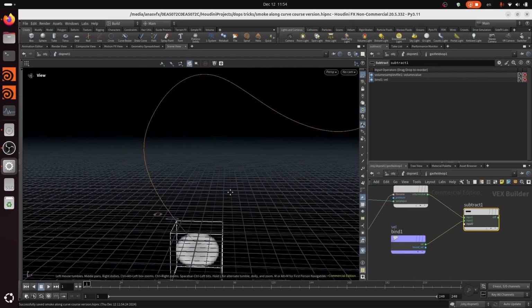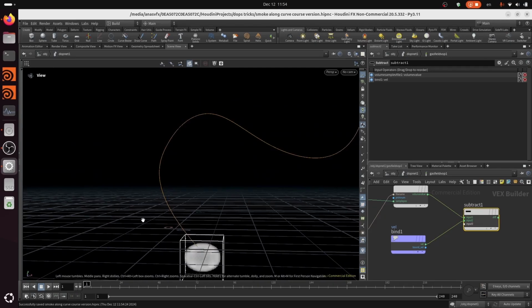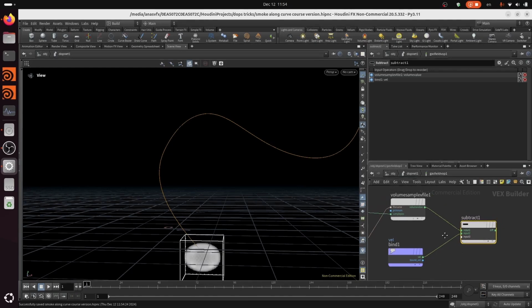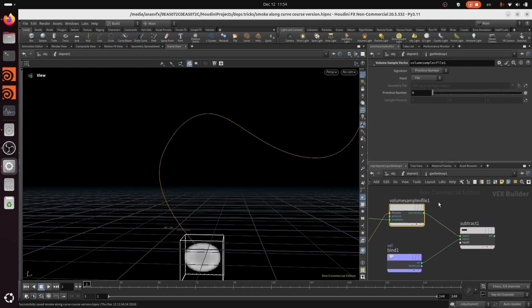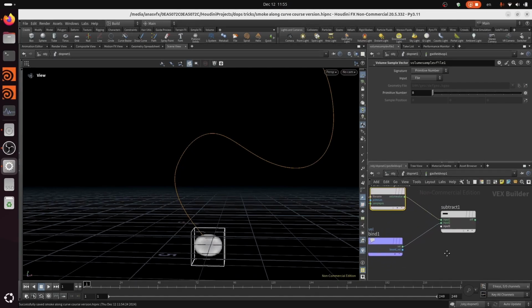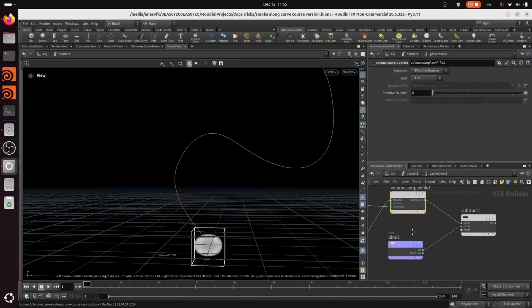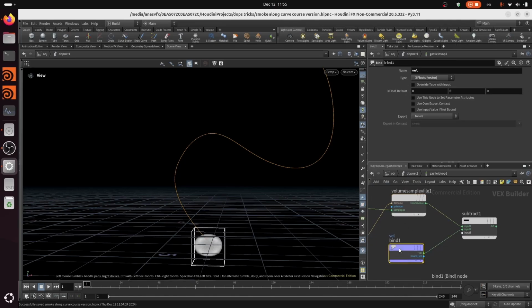If the difference between these two forces is larger than or equal to 4, for example, we want this velocity field from the subguide to affect our simulation more strongly, or to be dominant in our simulation. But if the difference is between 0 and 4, we want the velocity field of the simulation to be dominant.